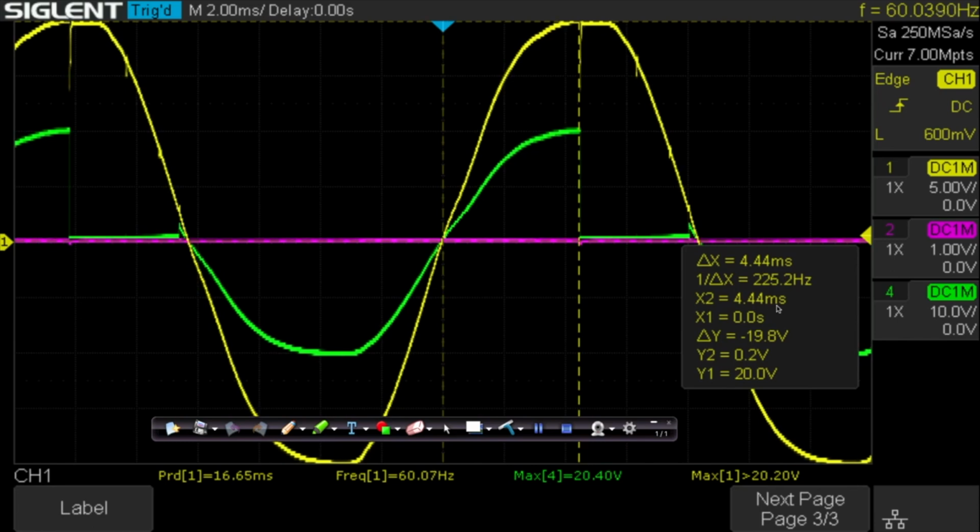And you can see that's pretty close. So let's turn it all the way here. I'm increasing the resistance of P1, so I'm making the SCR wait longer in the cycle. It takes more time for the capacitor to build up a charge to fire the UJT. I'm going to push it all the way. That's as far as my adjustment goes.